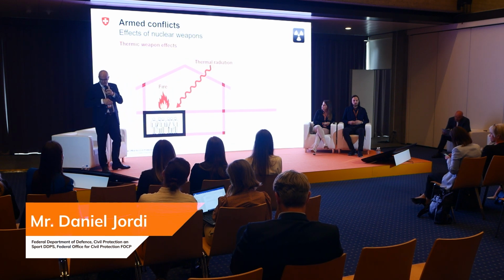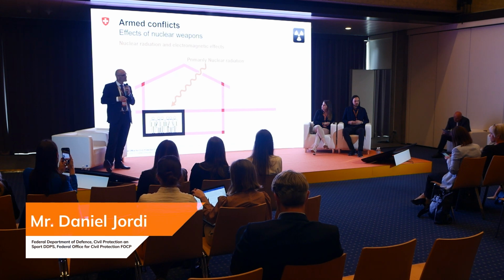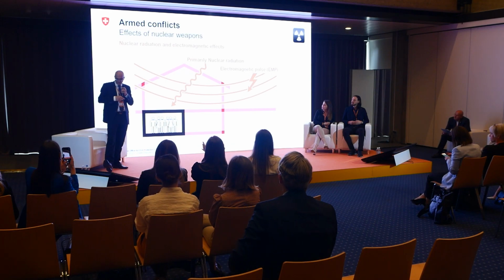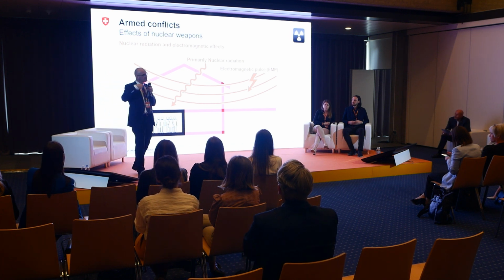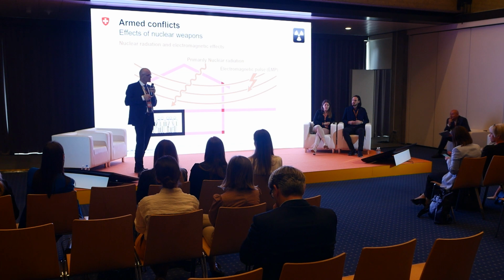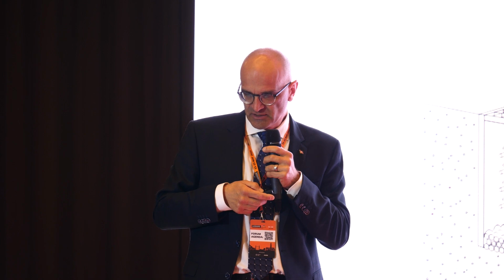Debris we had before, thermal radiation, fire, and the primary nuclear radiation protected by the concrete, which keeps away a good part of the radiation. They are protected against the electromagnetic pulse, so the lamps in there or the electric installations are still working. That has to be tested. And the radioactive fallout, we have aerosol filters in the filtration systems in there.